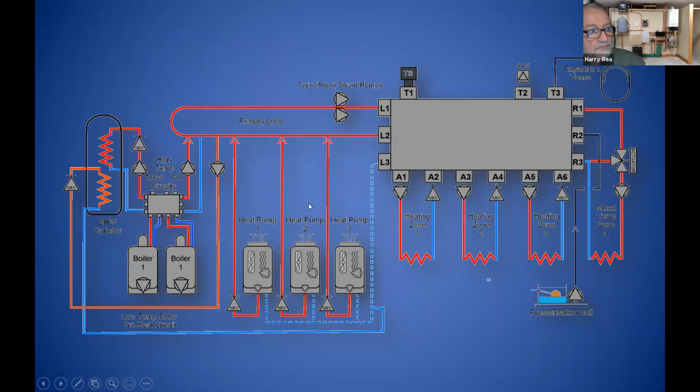Here's another, we did this job and I just could not get over the running costs. It was in a hotel, and this is going to take a bit of explaining, but it really is very good. So we actually ended up, if I'm not mistaken, with something like 8 heat pumps. There were 8 heat pumps, and they were being fed from a very large manifold where the cold water was taken down, and a sequencer was bringing in whatever heat pumps were necessary and feeding a primary loop.